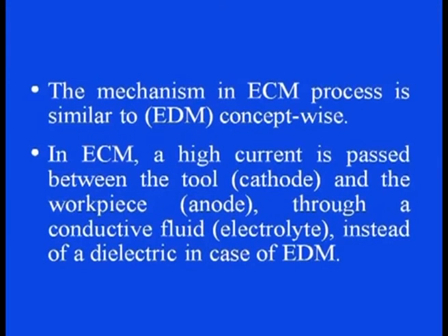The mechanism in the electrochemical machining process is similar to the EDM process, concept-wise. In ECM, a high current is passed between the tool, which is the cathode, and the workpiece, which is made the anode, through a conductive fluid, which is also called the electrolyte, instead of the dielectric in the case of EDM.